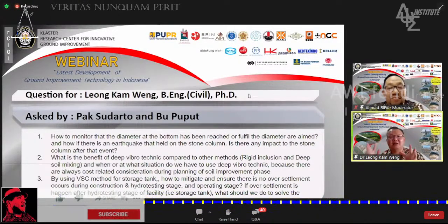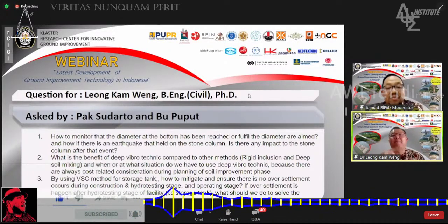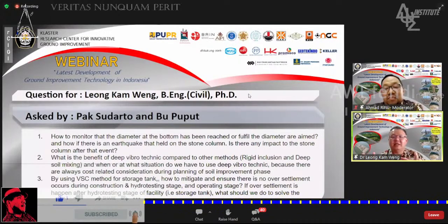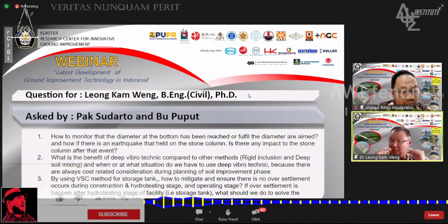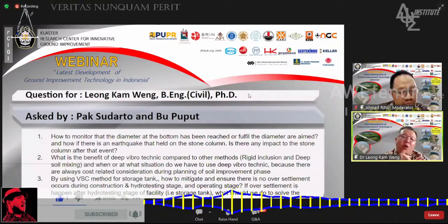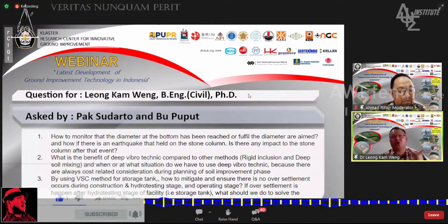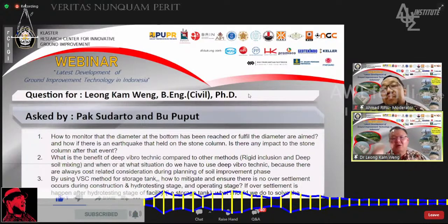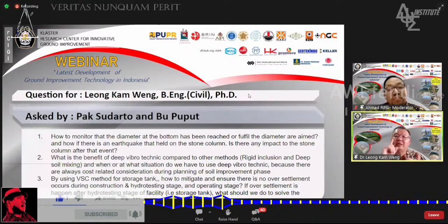The reason is that the more you know about the soil risk underneath the structure, the better you can mitigate this risk early on. If you know the soil risk, then we can design and change the treatment intensity across a certain tank, so that the differential settlement can be better managed during the design stage. So that's point one. Point two is that during the actual construction, you need the right QA/QC to ensure that each column is installed to your actual design depth. That will help to mitigate the risk.